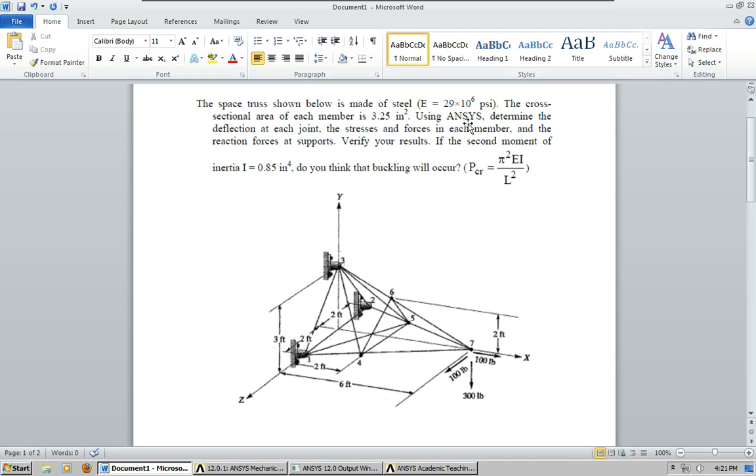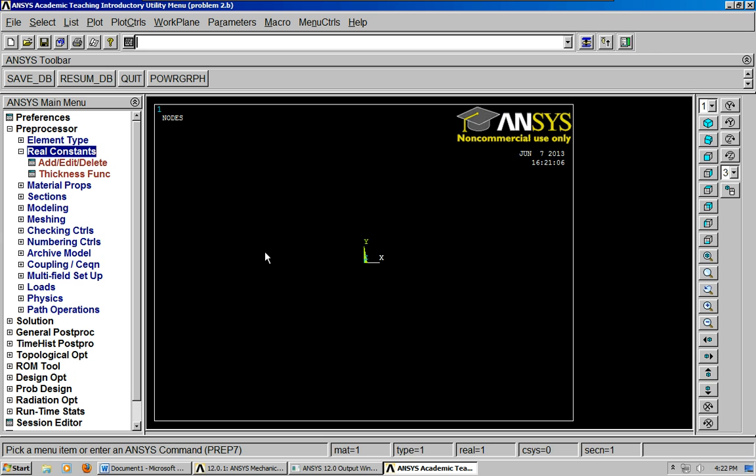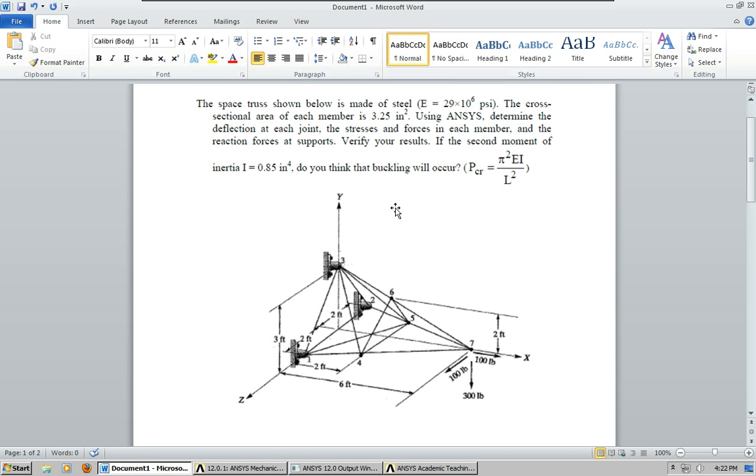So over here in the geometry there are feet. Make sure you convert those to inches. That's always true with Ansys Mechanical. You can use either imperial or SI units, but you have to make sure that you're consistent, using meters, or in this case inches.